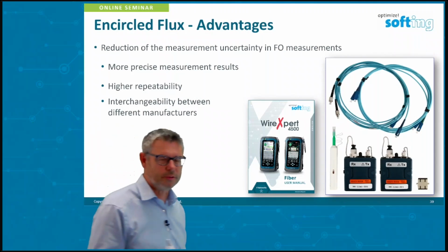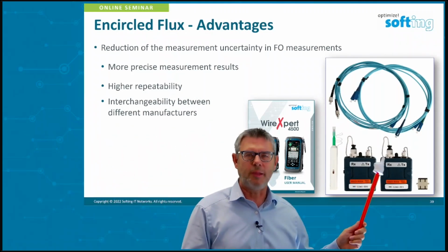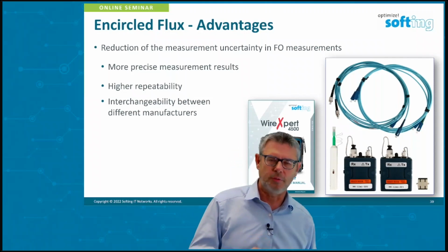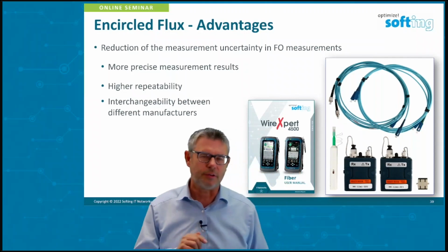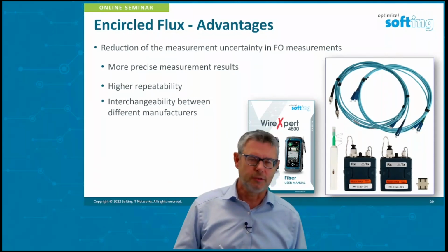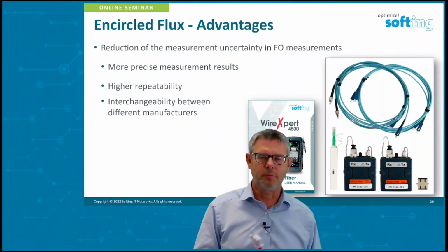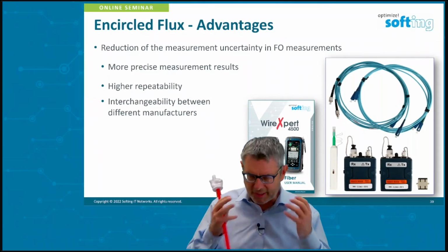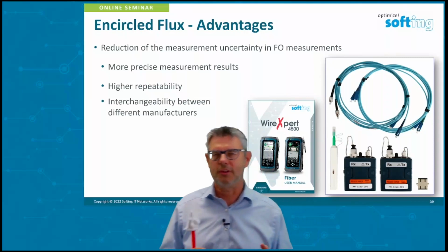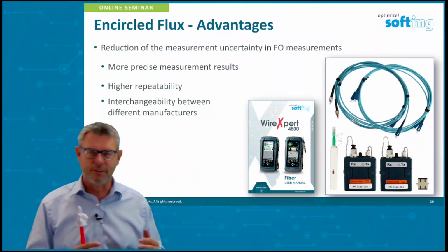You see what's very important here in the multi-mode is removable adapters here to match on the receiving side always the test connector of the fiber optic link you're going to test. What's also included for us is very important here, this cleaning stick. We want to be sure that everybody gets kind of awareness. Make sure that all the connections are really properly cleaned before you do your first connection, okay?